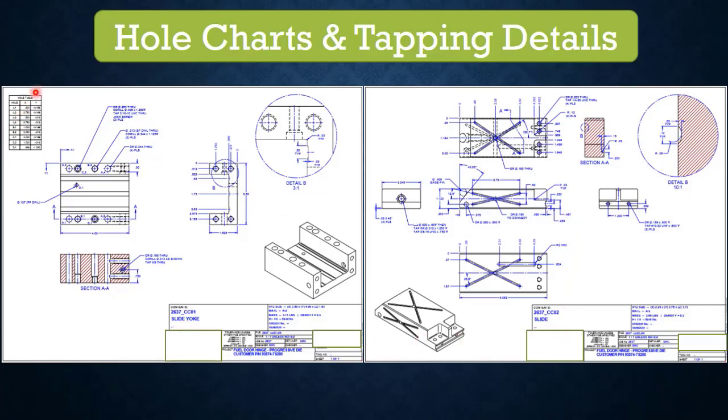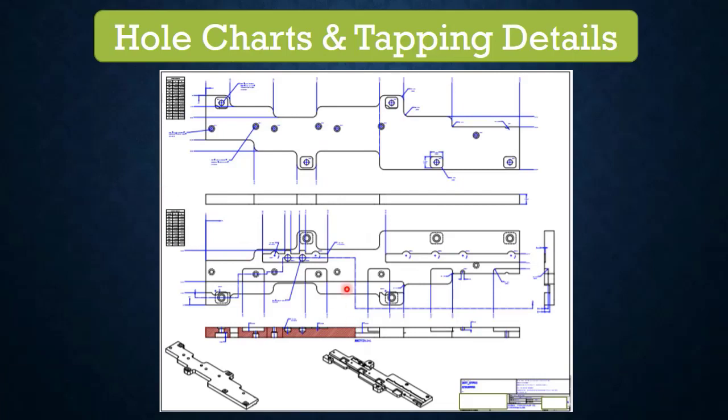Similarly, in every drawing, whenever there are more holes, we make a small x y axis table, so that the operator is able to finish them quickly without error. And then this is the stripper plate for the process.